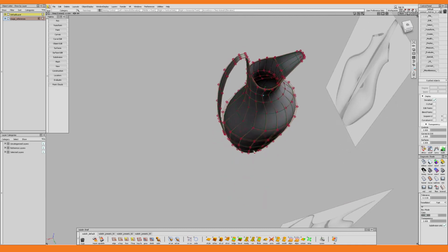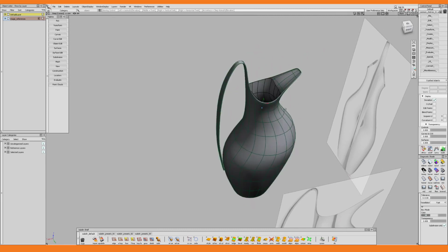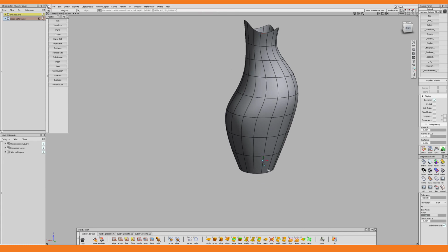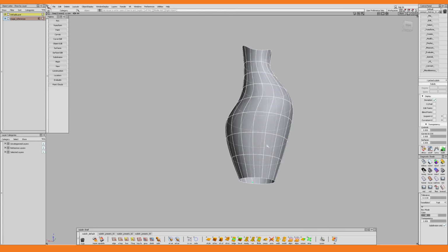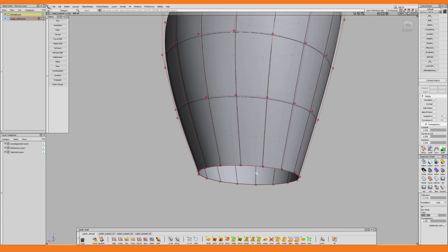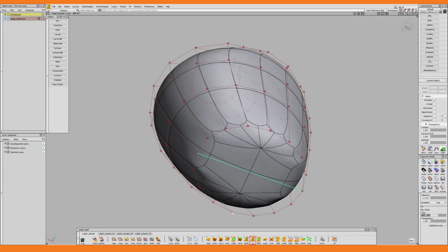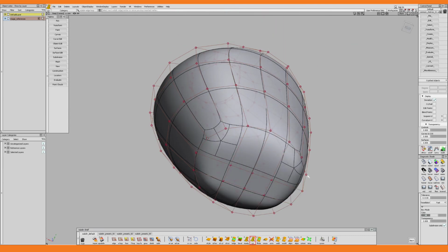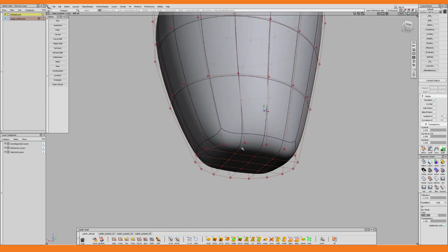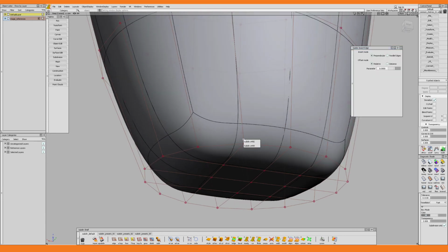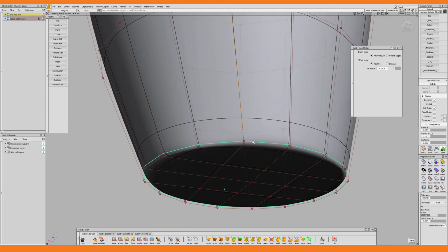And here I almost got ahead of myself, since before we can connect the inside and outside, we first need to fill the hole in the bottom of the inside. So let me isolate this once again. Turn on the controls, and then pick edge loop. And then I simply use the fill hole tool in conjunction with the cut tool to create the cap for the cylinder, just like we did before. And we mustn't forget to add the edge loop to create the crease line as well.